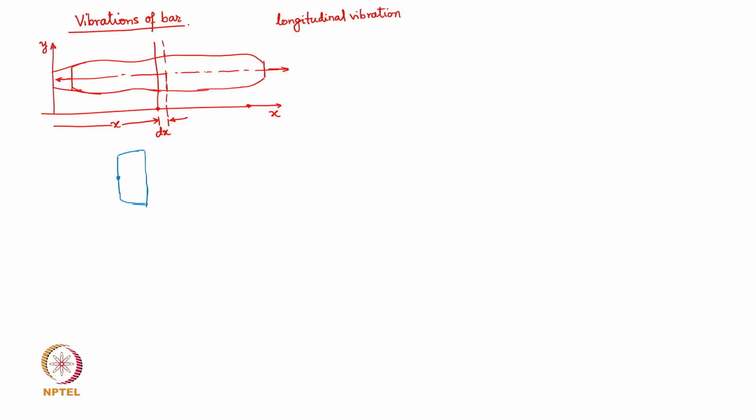Now under the continuous action of all the forces which are set up in the bar, we find that the bar is under equilibrium under the action of these internal forces which are set up at position x. The original distance here is dx, as we have taken an infinitesimally small element out of the total bar of this continuum, and let this get stretched under the action of these forces.